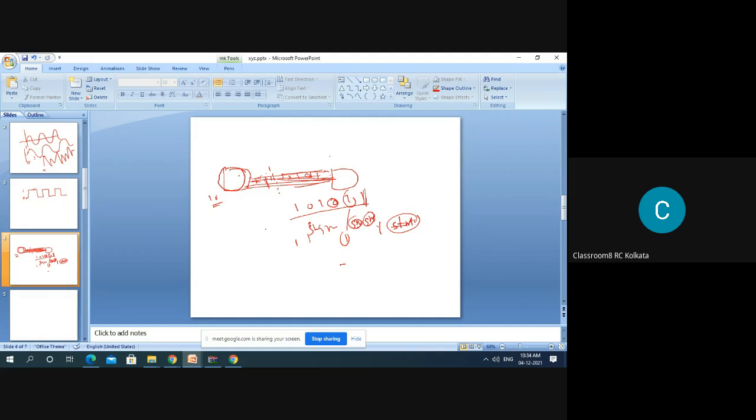The term asynchronous is used to describe the process where transmitted data is encoded with start and stop bits, specifying the beginning and ending of each character. This additional bit provides the timing or synchronization for the connection by indicating when a complete character has been sent or received.